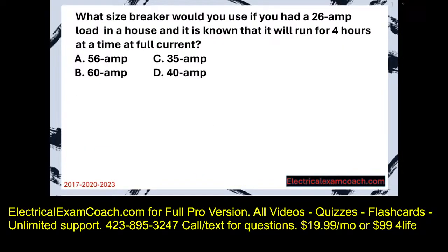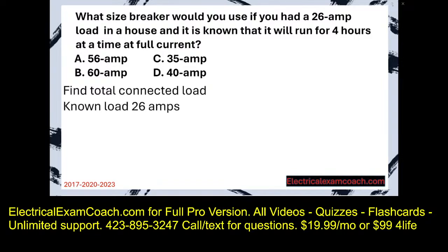What size breaker would you use if you had a 26 amp load in a house and it's known that it will run for 4 hours at a time at full current? Step 1, find the total connected load. Our known load as of right now is 26 amps. Now we got to check for demand factors.